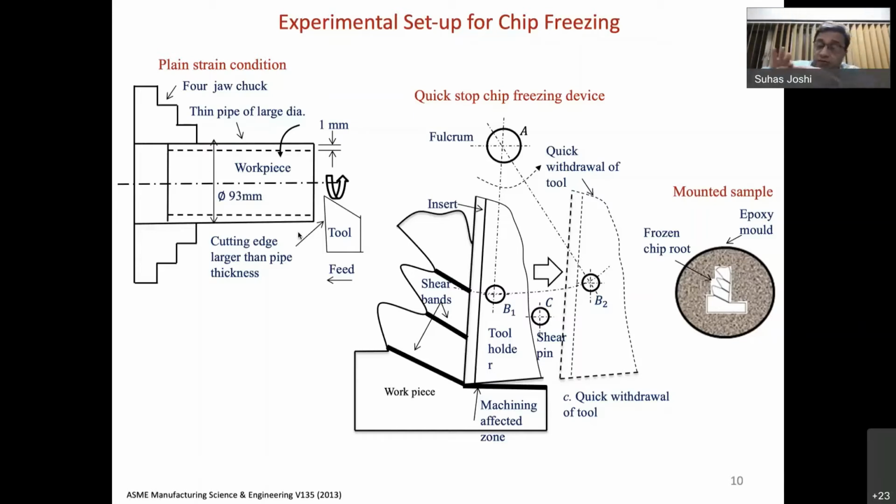The tool is resting on this pin, and at one point, what we do is hit the tool from the top so that this pin shears off. This pin shears off, and the tool is actually withdrawn from the machining process. So the tool is resting, and then suddenly the tool is withdrawn, and the chip segment remains attached to the